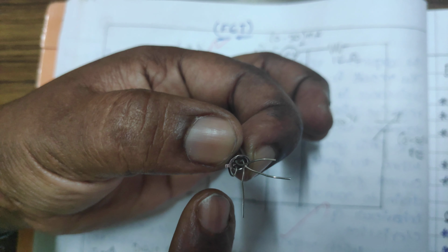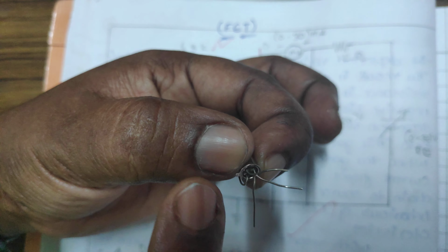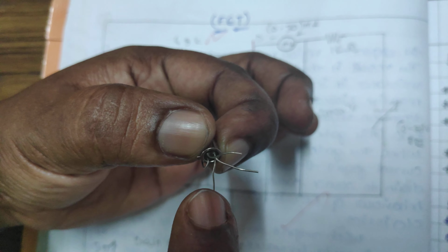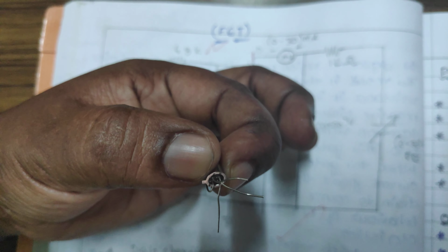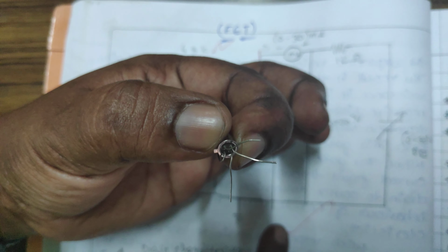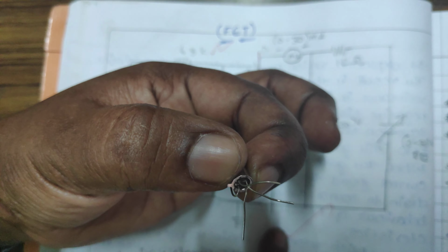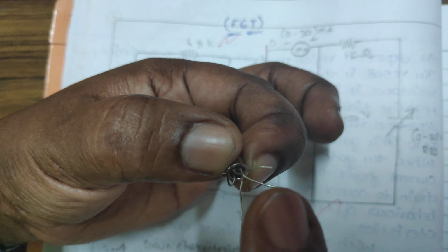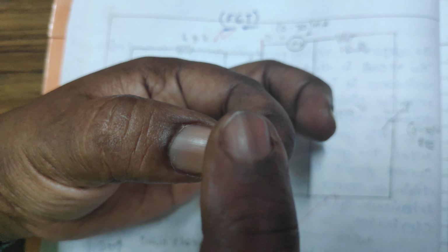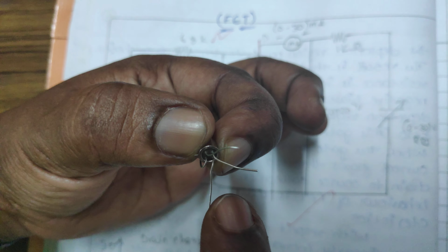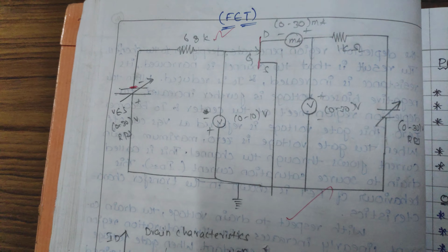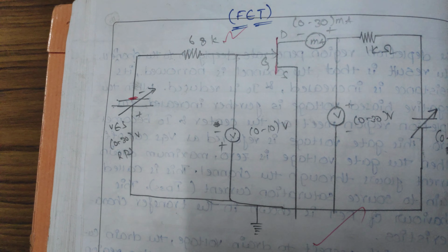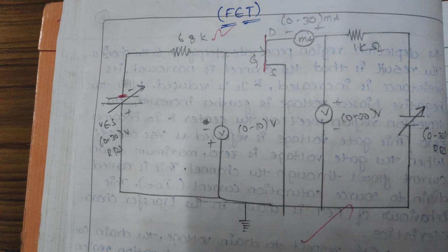While we are giving the component also, we will be folding and giving it to you. So you can use only the 3 terminals, source, drain and gate. In BJT, which you would have done the experiment, you have 3 terminals, emitter, base and collector. Here you have source, drain and gate. So after connecting the circuit as per the circuit diagram on the breadboard, let us go to the setup.